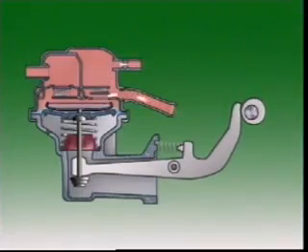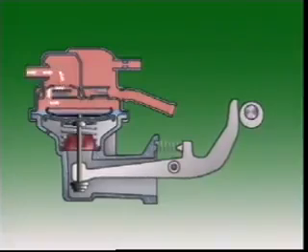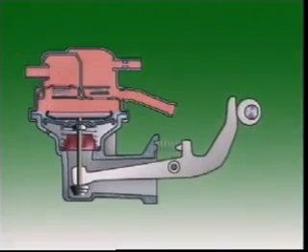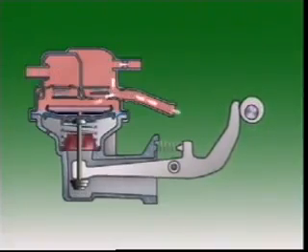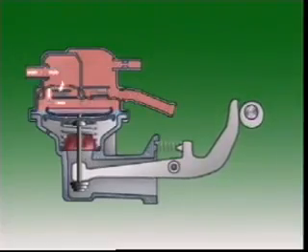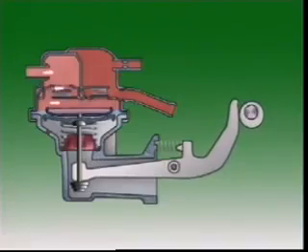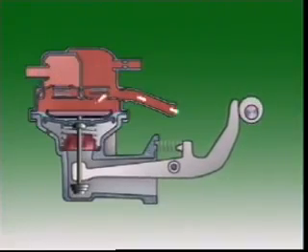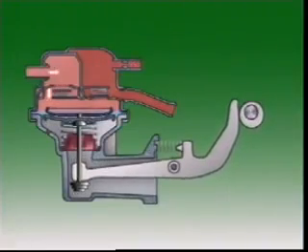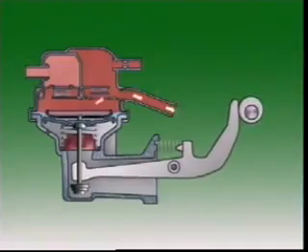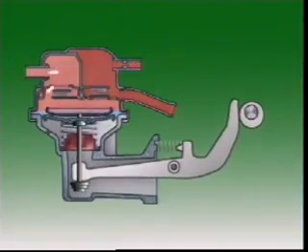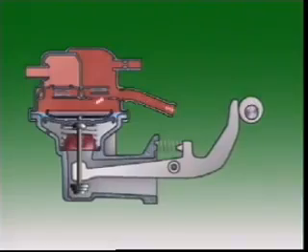into the carburetor. When the engine needs more fuel, the diaphragm moves through a long stroke to pump a lot of fuel. When less fuel is needed, pressure builds up in the fuel line to the carburetor and in the pumping chamber above the diaphragm. The diaphragm spring can't push the diaphragm up so far, and the pumping stroke is reduced.